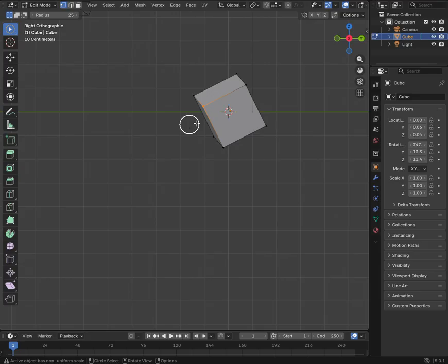To do this, you need to select the thing that you want to extrude and then press capital E, likewise. So you can see the orange sign there. Step number 10 is edge loop slide. So this allows you to make a cut in the mesh, letting you modify it further.